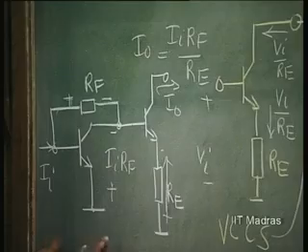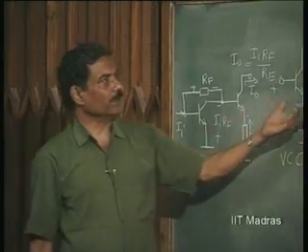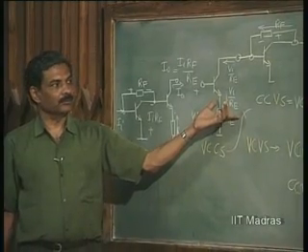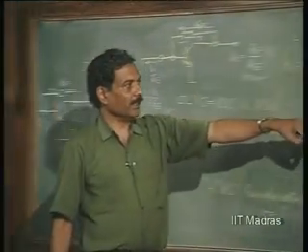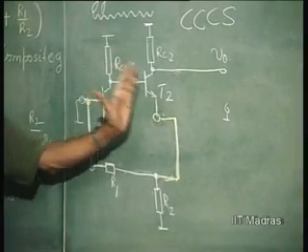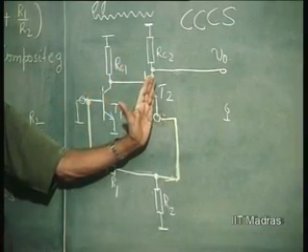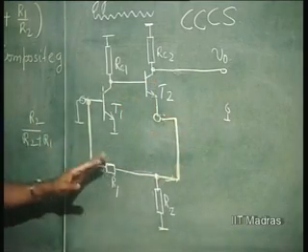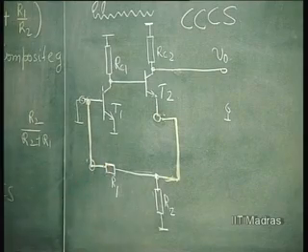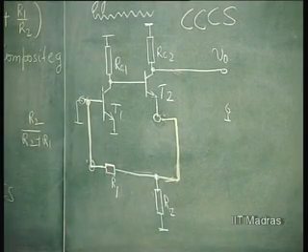So, you see these two networks are not networks with overall feedback. Here this current controlled current source has overall feedback. Two transistor amplifiers are cascaded first and then the output current is fed back to the input using this network. Here it is not done that way, these have local feedback.